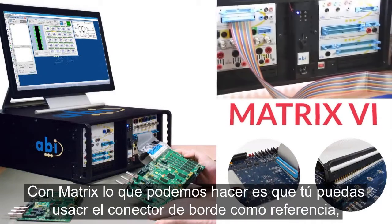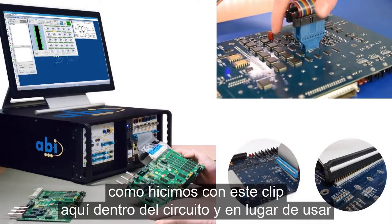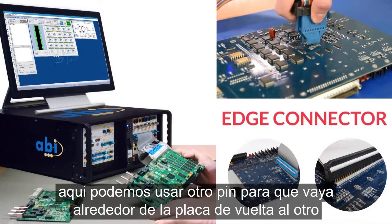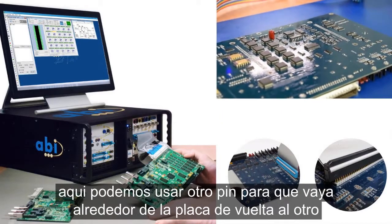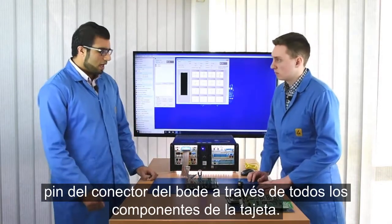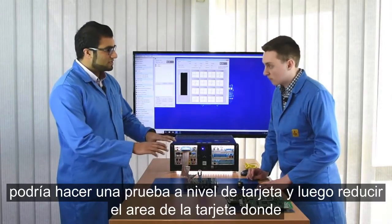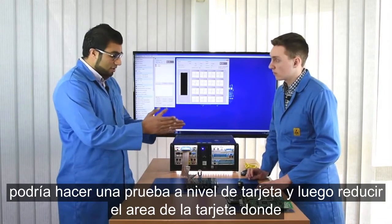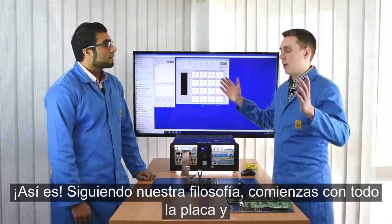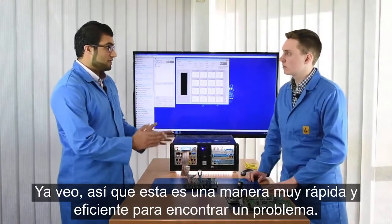With matrix VI, you can use the edge connector and do the reference like we did with this clip here, inside the IC, and instead of using an area on the board like a ground or another component and getting the circuit there, we can use another pin, so it goes around that circuit back to the other pin across all the pins on your edge connector. Would you say that this is a good way of trying to isolate what the problem is? So you could do a board level test and then narrow down the board itself to find the problem. Absolutely. Our philosophy is, you start system-wide and then you slowly narrow it down to where the fault is. So it's a very quick and efficient way to find the problem.